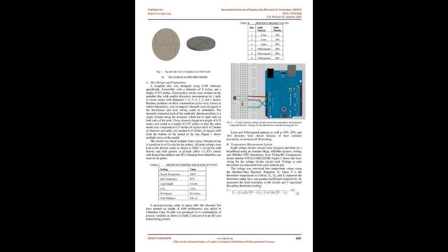Zhang, Wang, Yu, and Den numerically analyzed the influence of 3D printing conditions on heat transfer. [18] Their research offers an extremely specific mathematical model during and after printing. However, the conditions set by the researchers are impractical for use of the model in any other situation. They assumed the objects printed were pore-free, essentially a 100% infill, which is impossible to recreate because of the slight errors in the extrusion of plastic from a 3D printer. They also neglected heat radiation within the object, polymer crystallization and energy balance, and thermal expansion.